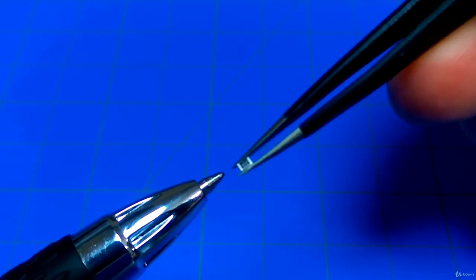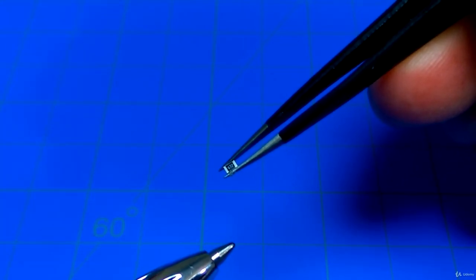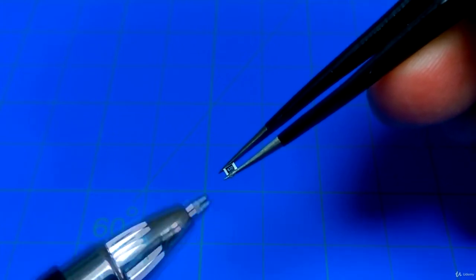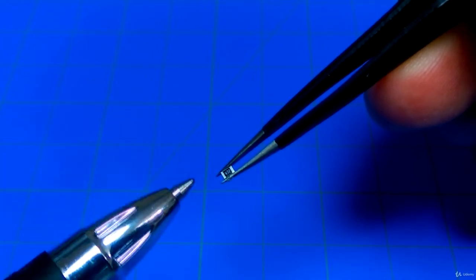You can see the number on there, 472, and let me get it back and zoom. So it's 4.7 times 100, so that's 4,700, right? And the 2 is again the multiplier. The smaller they get, they have no writing, and so if you lose it, you have no idea what the value is anymore. So if you lose the packaging or you forget what the value is, you have to measure it. And again, how do you measure something like this?